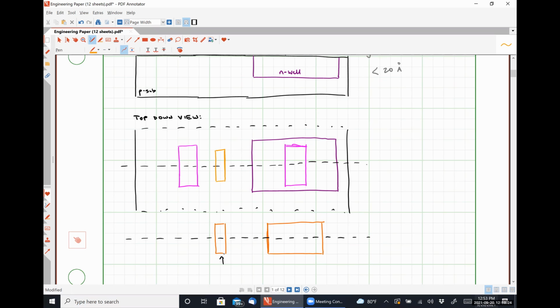And so we have this extraordinarily heavily doped region, so I'm going to call this part right here P+ region, sitting inside of our p-type substrate. What that's going to allow us to do using subsequent processing layers is to electrically bias our substrate to a specific voltage level using a metal semiconductor junction known as an ohmic contact, okay?